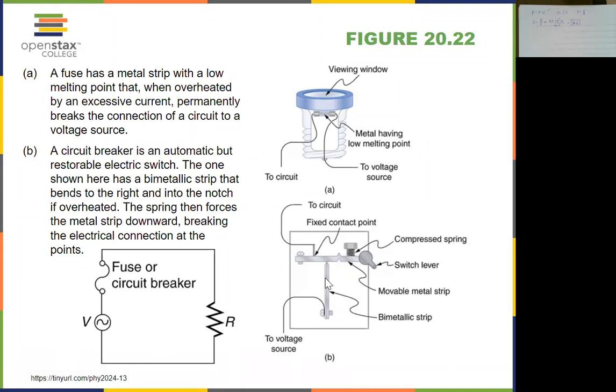The two materials respond to temperature change differently, meaning they expand differently, so it will bend this way. Then this one will drop off and cut the power, so the switch lever will be cut off. So there are two ways to prevent thermal hazards there.